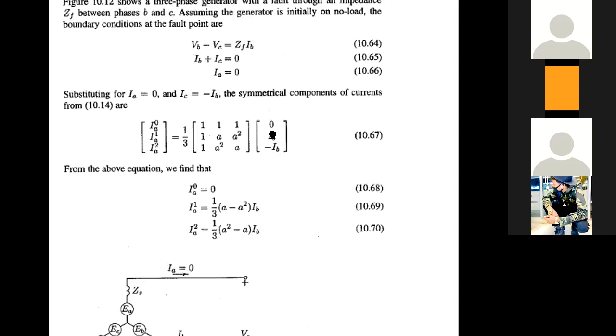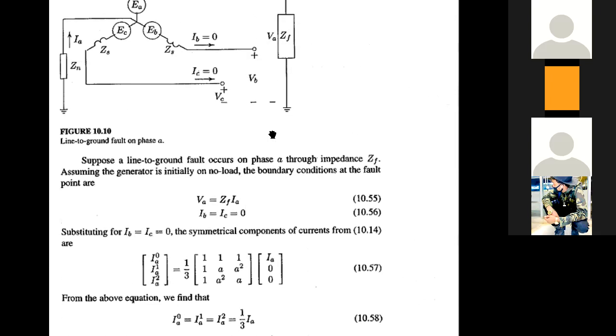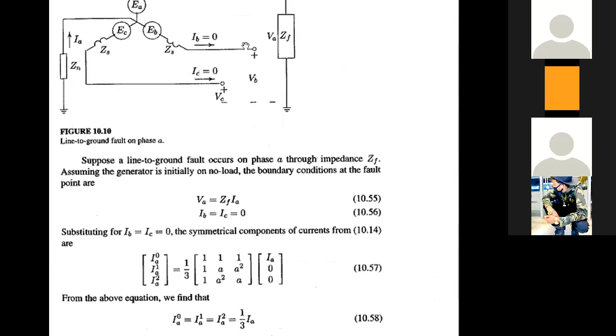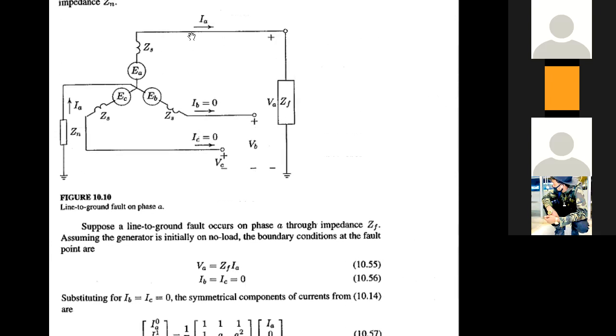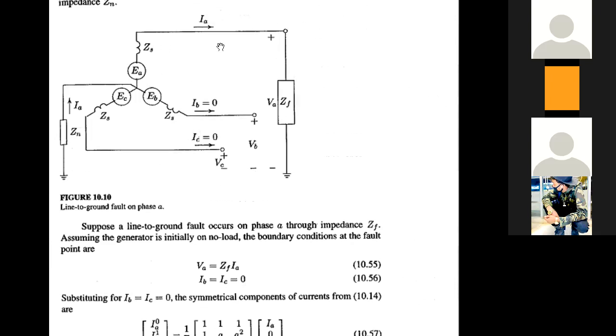Now we can check the earlier class lecture, how we can put the information there. If it is another type of fault, which is single line to ground, what will happen? In the single line to ground case, only the IF current will be there. IB and IC will not be there, because you have only the fault path through that phase.